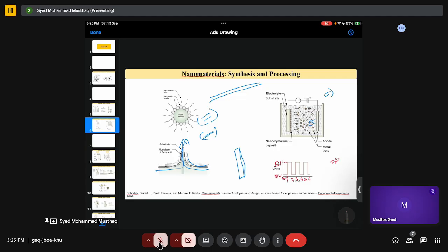So whenever you do that, the film that was getting deposited, first it gets deposited here, then because we are breaking the circuit, not shorting, the next thing that grows will be here. So that's how the whole layer will be uniform, because we are supplying a pulse, and there will be only small crystallites forming everywhere.